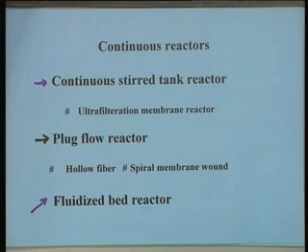So, overall in terms of reactor performance it can be considered almost similar to that of a CSTR. Now, there are two major modifications which have been proposed in the case of plug flow reactors. While the conventional systems, as we have seen, use a packed bed and feed the substrate either at the top of the column or at the bottom of the column, either combination is feasible, but they also may have some operational problems. The two major modifications which have been proposed and have been used in enzyme catalyzed reactions, one is a hollow fiber reactor.